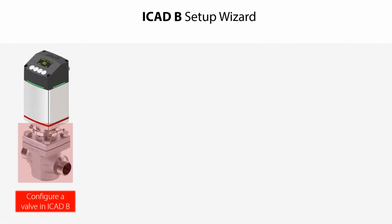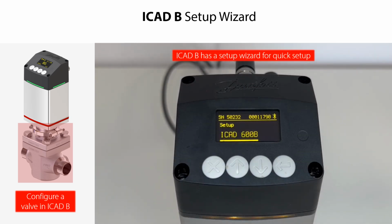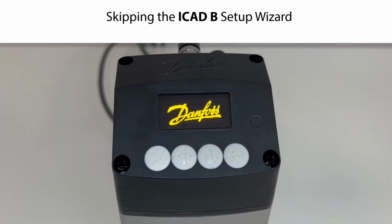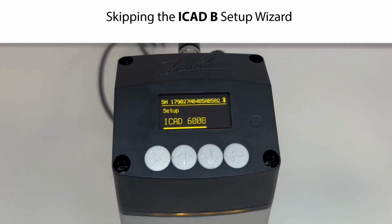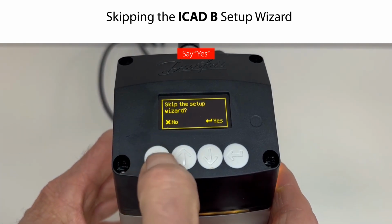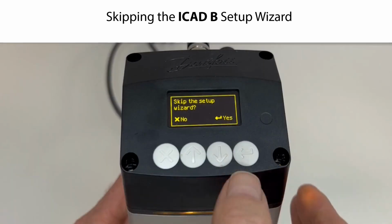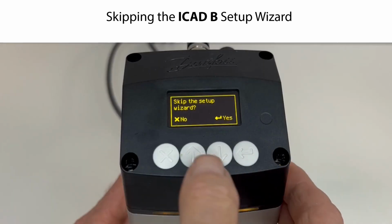Before we can operate the ICAD B and the valve onto which the ICAD B is mounted, we first need to configure the valve in the ICAD B. The ICAD B has a setup wizard as default ready to support you to do a quick ICAD B and valve setup as seen here. Should you wish to skip the ICAD B setup wizard and instead manually set up the ICAD B and valve, then press exit and say yes to skipping the setup wizard. However, let us now do the quick ICAD B and valve setup by using the setup wizard.